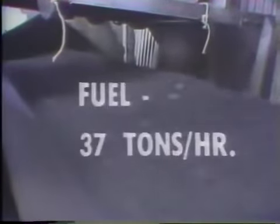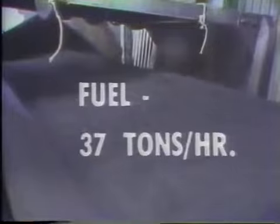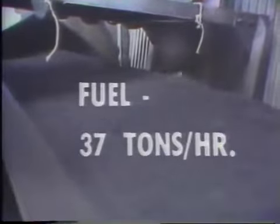The fuel requirement for this unit producing 100 megawatts is around 37 tons of coal per hour. To burn 37 tons of coal per hour, the operator has to mix it with about 1.5 million pounds of combustion air per hour.